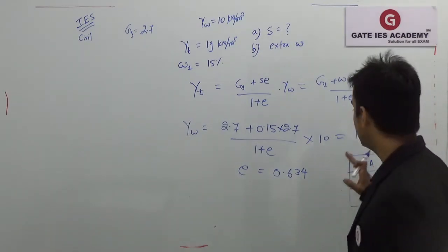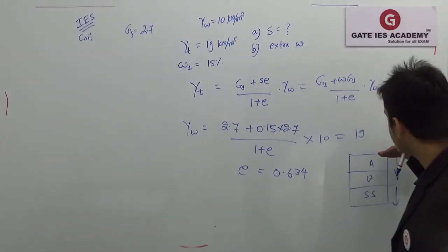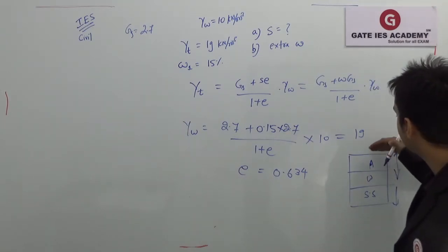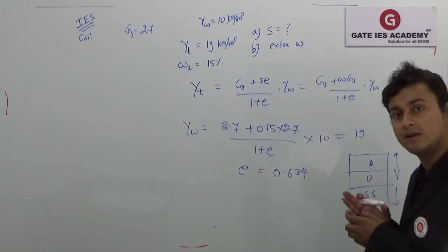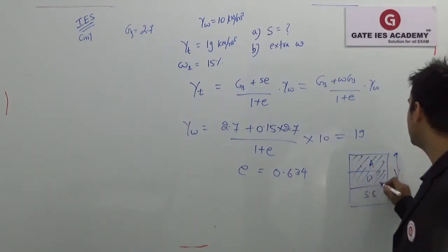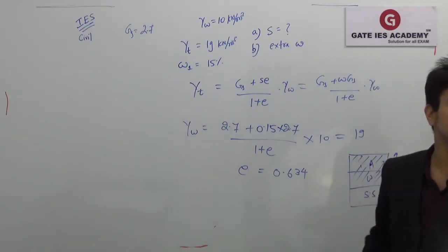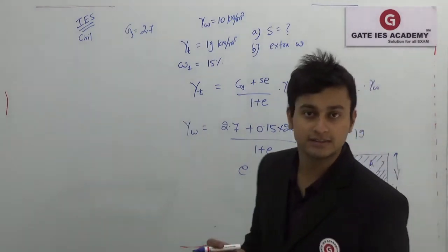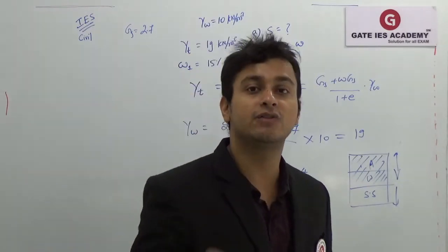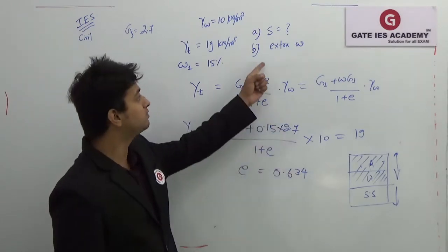It would increase only when the net addition of water goes beyond the air level. But as a limited system, we will fill the water up till this point, and this can only become water. So the voids are constant, the volume of the system is not increased, therefore the volume of the voids is constant and the void ratio will be constant. So this E can be used in the next part also.